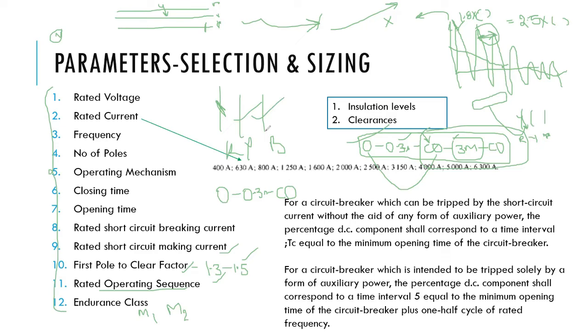There is a change in poles. Pole here means phases. One phase is open, one phase is not open, so the three phases are unbalanced. One is open, the other two are not open. So there is a pole discrepancy. Based on the pole discrepancy concept, the breaker will operate the other two phases also. So the breaker is opened.